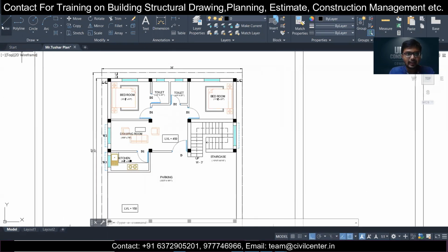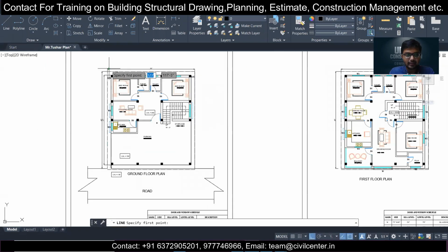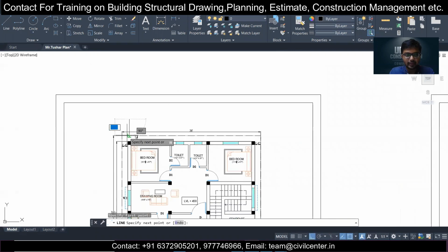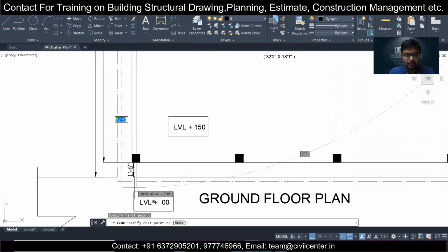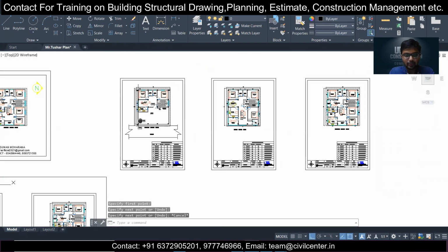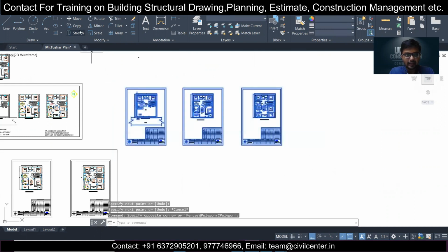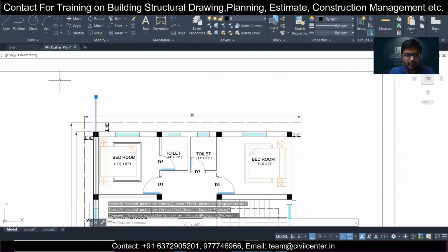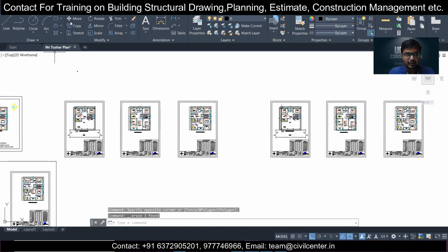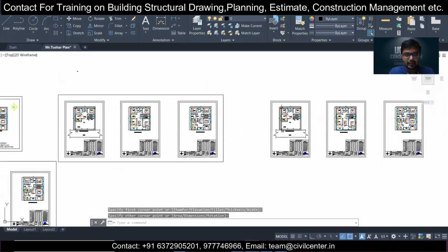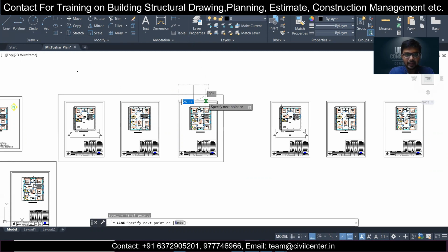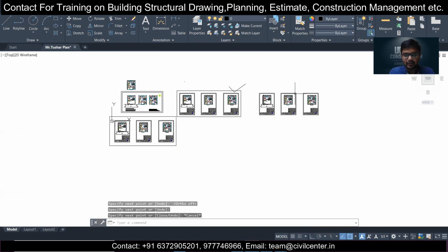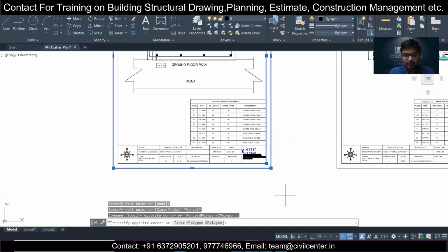So basically, let me just create a line here and start from here. And I'm going to go for the vertical lines. Before doing that, I can select this and copy it, because I don't want to disturb this in my CAD file. So I'll make a rectangle around it and call this the original file. I can give a tick mark to identify that this plan has been unchanged, so I can make whatever changes I need to this particular plan.